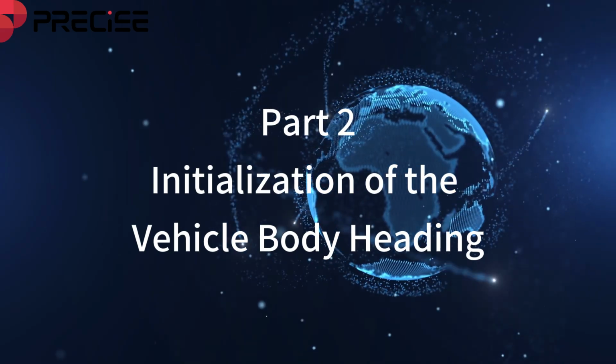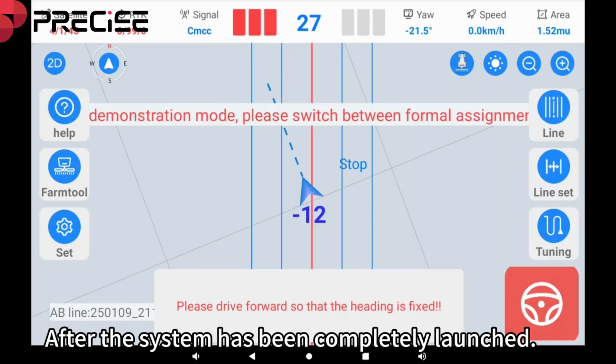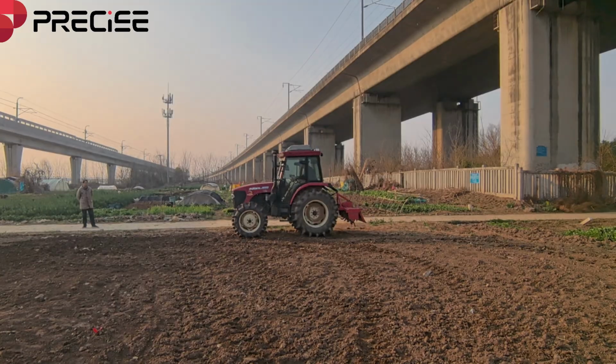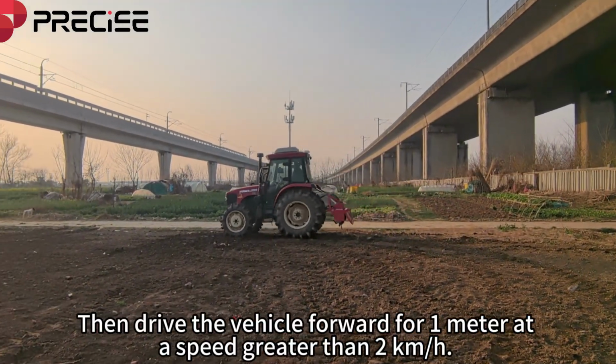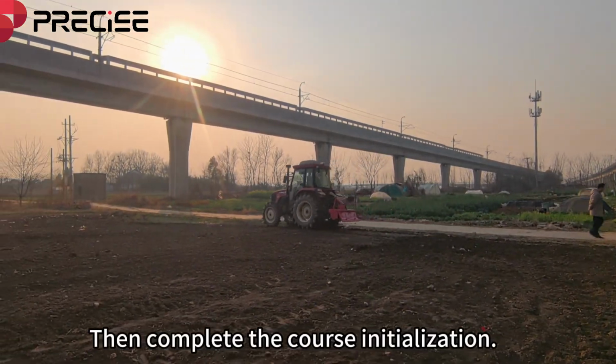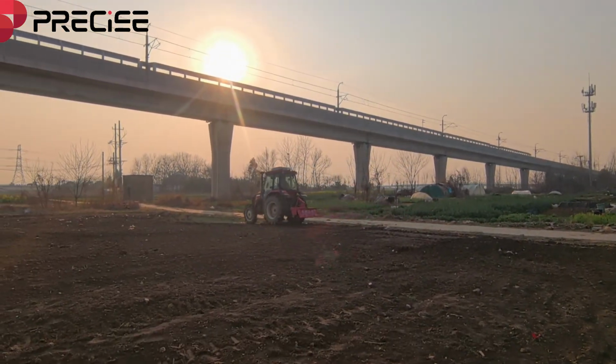Second, initialization of the vehicle body heading. After the system has been completely launched, please drive forward so that the heading is fixed. Then drive the vehicle forward for 1 meter at a speed greater than 2 km per hour. Then complete the course initialization.